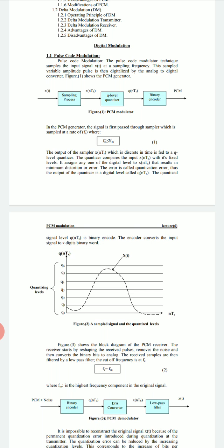In the frequency form: a band limited signal of finite energy which has no frequency component higher than W hertz may be completely recovered from its samples if we take the rate as 2W samples per second.